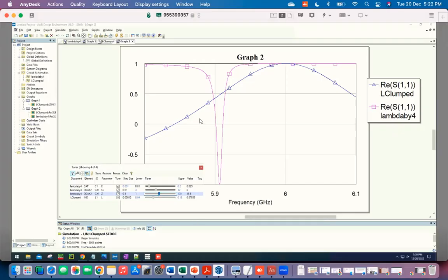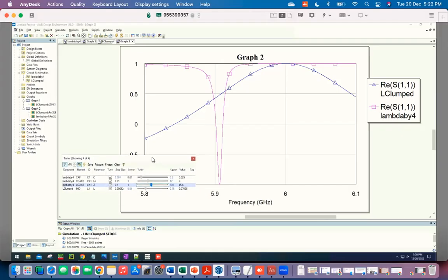So that's just what you were saying earlier was also sort of correct if one took a leap of faith. But the precise statement is because now the total resonant frequency depends on the combination of both the external capacitance and the capacitance contributed by the second transmission line. So when you change that, you get different frequencies.